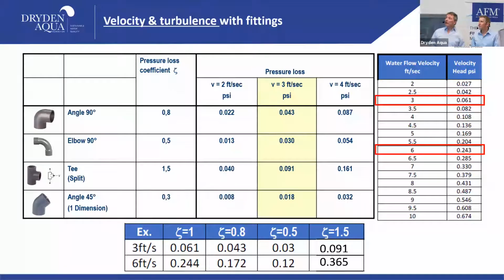So, is that clear in America, Sean? Oh yeah. As we said, we're making it complicated so we can make it simple at the end. Good. Once you understand it, then you understand lengths and try to avoid fittings. If it's needed, it's needed. But especially try to avoid those fittings with a very high coefficient. Just go down with the speed by making the fitting bigger, and you compensate, and you will be fine.